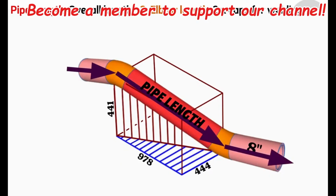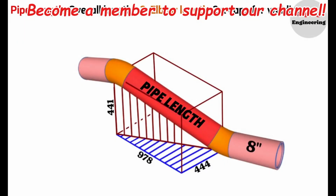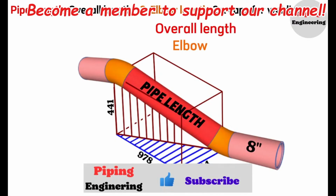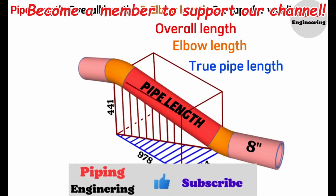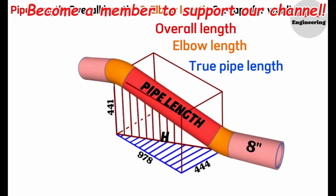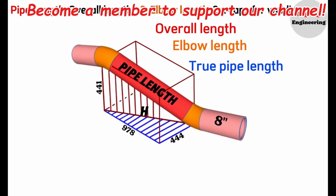During the double rolling of a pipeline, two right-angle triangles are formed using dashed lines. We will use these triangles to calculate the overall length, elbow length, and true pipe length. Let's first label the hypotenuse of the horizontal dashed line right-angle triangle with the letter H and then determine its length. To find this hypotenuse, we will use the Pythagorean theorem.